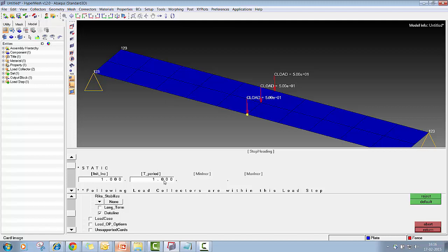So had it been a case of a nonlinear geometry or nonlinear material, we need to define some very low value of initial increment. Then the load will be slowly ramped up to the end time period of 1.0, so that the nonlinearity in the simulation will be captured. So that is for nonlinearity problem. So here we have only straightforward linear static analysis, just define initial increment 1.0 and end period as 1.0. So we are done with this step 2.